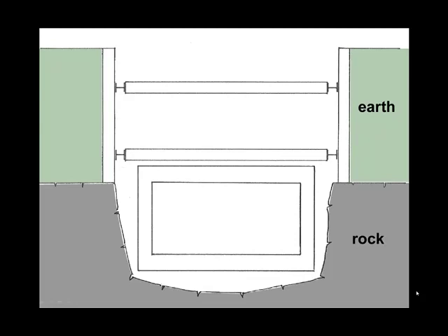Very difficult to control exactly how the rock is going to split. There are procedures of line drilling, pre-splitting to ensure that you do not undermine the earth layer above the rock. But in general, you will get a picture that looks much more like this as opposed to that theoretical look that you'll see in textbooks.